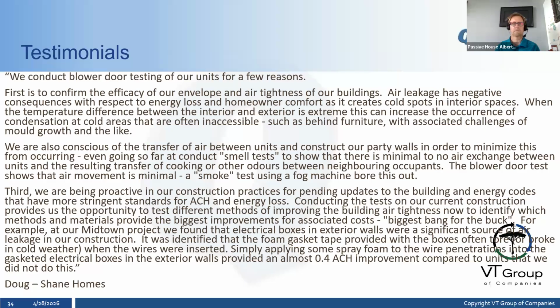They are happy with how it's being used. That's kind of the biggest thing, right? As long as the air gets stopped, I don't really care how it gets stopped. So if we can stop it with the poly and the acoustical sealant and compression, fantastic, great. You're planning on doing that anyways. If it comes to it where we need to put a tape on to stop that air movement, then that's the discussion we need to have. We need to have everybody on board for that. So usually we try and recommend it's cheaper, more cost effective, faster for everyone to use the poly and acoustical sealant. But if there are situations where tape's required,